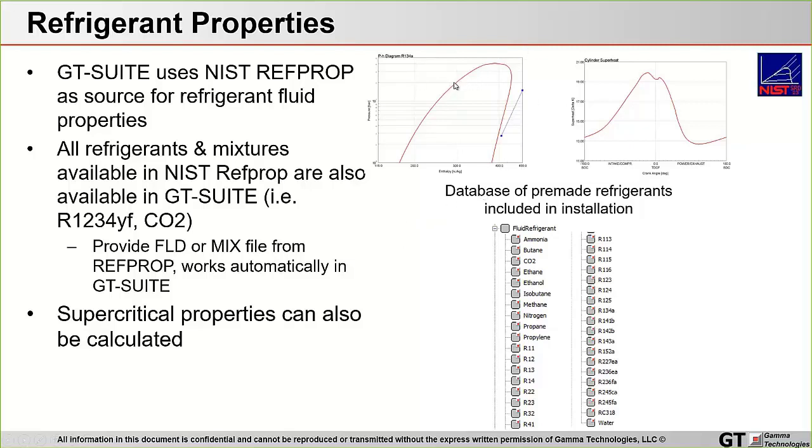And so that allows the fluids to operate dynamically and transiently in any part of any thermodynamic state, whether it's in the gas region or the liquid region or supercritical, or even inside the dome in the two-phase region. And so this is very important when you're trying to study a heat pump circuit where the fluid can exist in gas, liquid, and two-phase states.